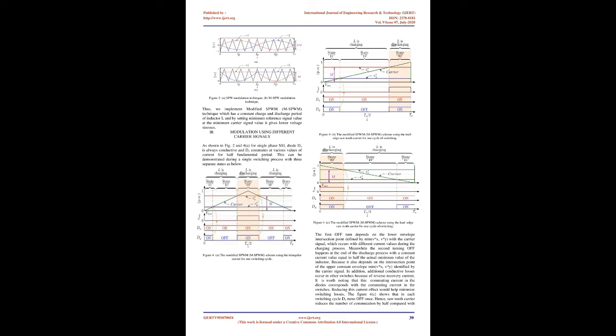In this configuration, single-phase operation allows the use of dual common cathode diodes in one unit as a replacement of using two separate diodes. This helps to achieve less parasitic inductance in these diodes' commutation direction. Furthermore, it results in fewer voltage spikes across the various switches and increases the overall efficiency of the inverter. 2. Working principle and control strategy.